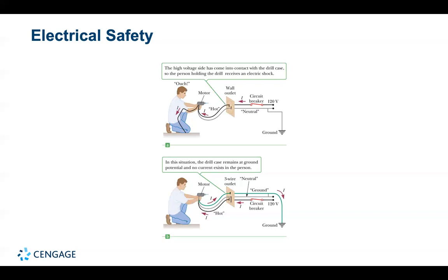Special ground outlets called ground fault interrupters, GFIs, are now being used in kitchens, bathrooms, basements, and other hazardous areas of new homes. They are designed to protect people from electrical shock by sensing small currents, approximately 5 milliamps and greater, leaking to ground. When current above this level is detected, the device shuts off, that is, interrupts the current in less than a millisecond.